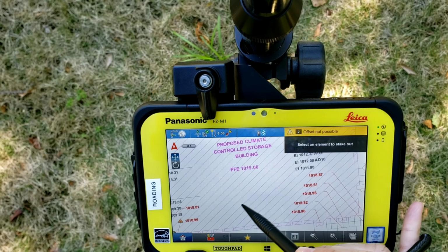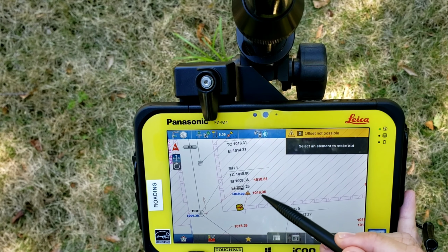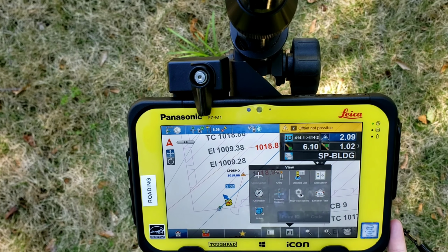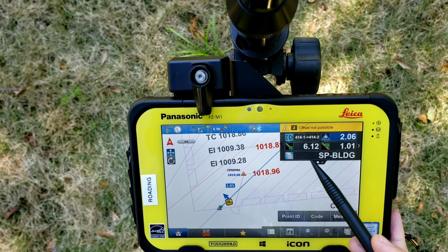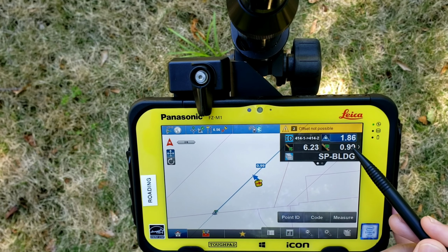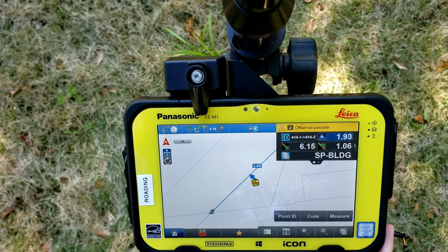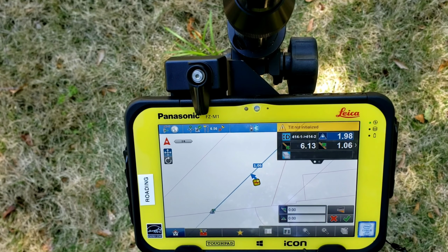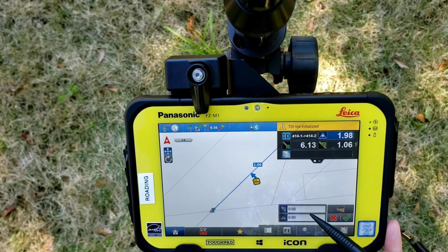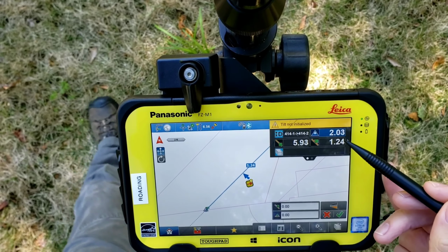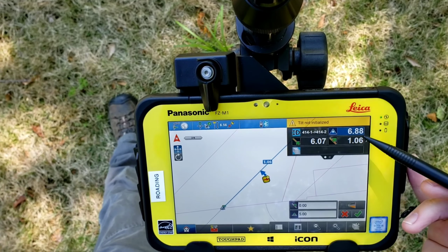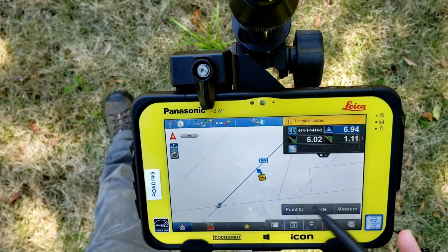So that's basically exactly like it shows. If you pick a line, right now you've got your station from your start. Turn my automatic centering back on. So we're at 6.12, we're right 1 foot, as you can see. 105, 105, we've got a fill of 187. If we change our elevation offset, it actually gives you elevation and you can do lines. So elevation's the second one, alignment's the top one there. We've got a fill of 205 right now, so obviously if I add 5 feet to it, I'm going to have a fill of 7. So that's how that works.